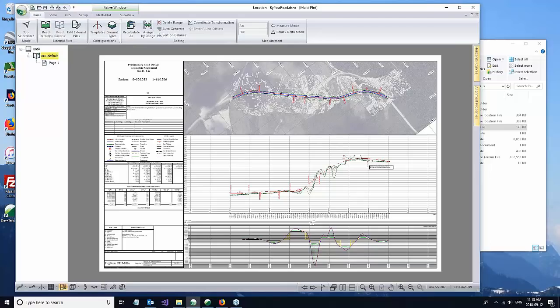So you'd end up maybe with a section that's kilometer 0 to 1.6 kilometers, and then the next page might be 1.6 to 2.6 or whatever. You would name the files appropriately, and you'd have to call them up when you're in the field, or change the scale. There's lots of ways to do it, but you will get one file per page.